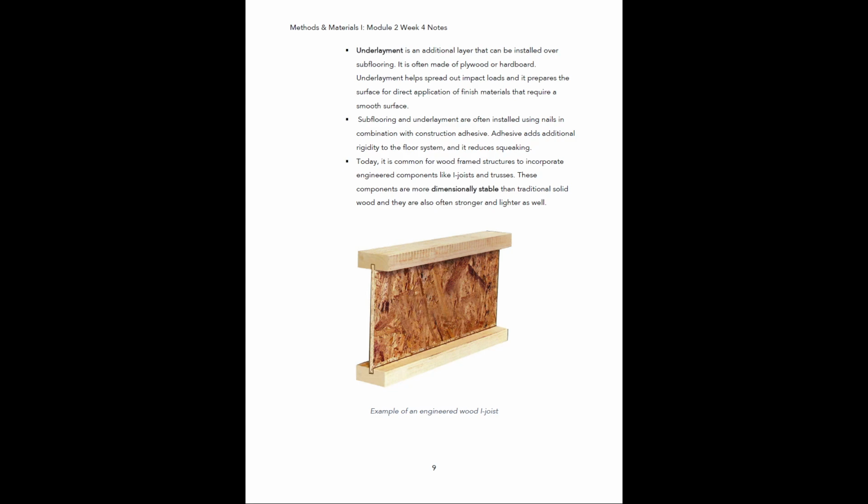The nails are there to just hold it fast, and it basically acts as a clamping mechanism while the adhesive dries. But the adhesive does most of the work, and the adhesive is good because it reduces the squeaking and it makes the entire system a lot more solid.